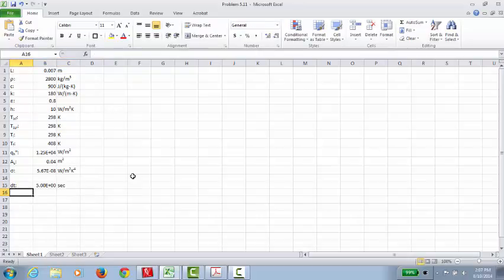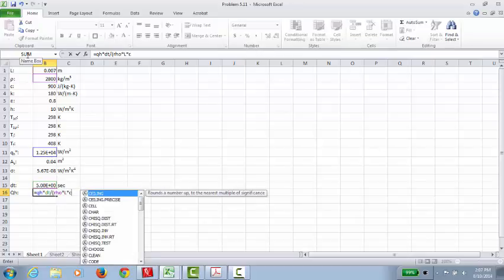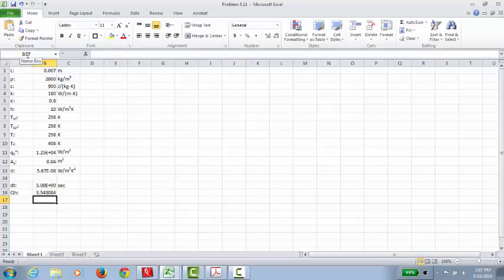We can calculate then what our capital Q sub h is using this dt, which we'll make sure we label. So capital Q sub h is equal to little qh times dt over rho times L times C. And again, the units for that are Kelvin. We can also calculate what the Fourier number is.